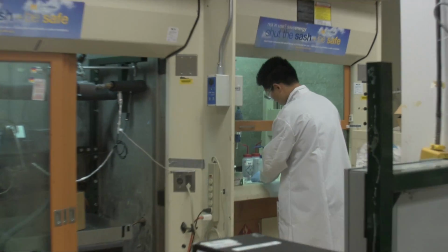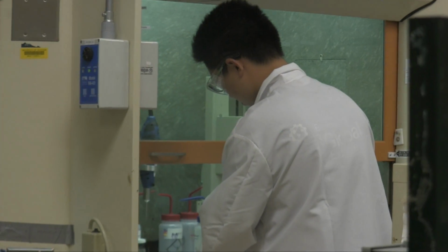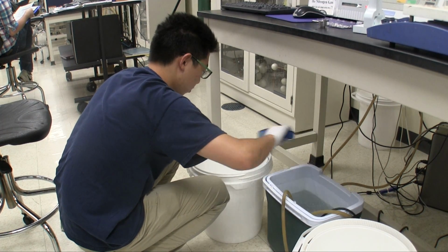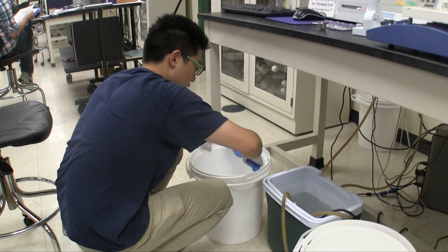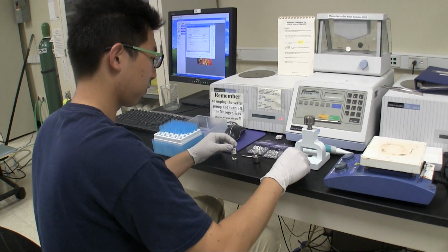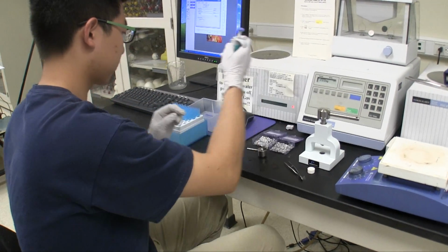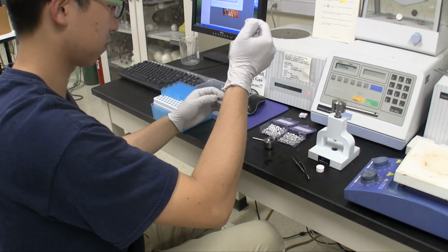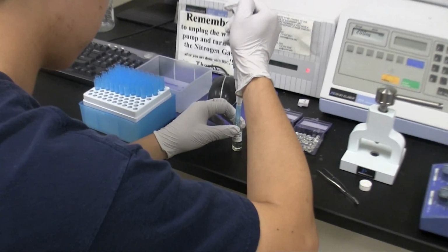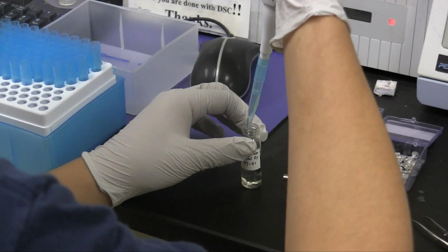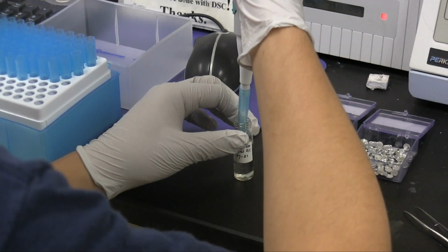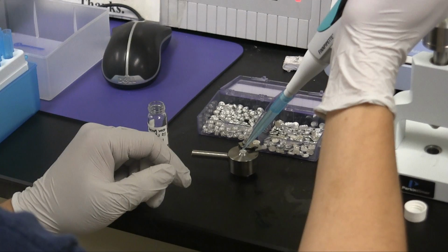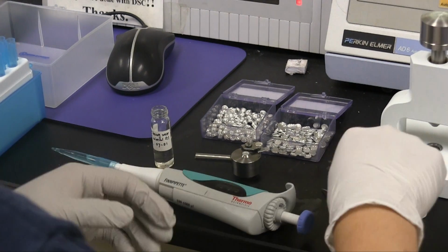My research can be divided into 3 parts. The first part of my research is to conduct DSC tests to get heat flow curves from different oil samples. I actually have several problems while doing the experiments. The first problem happened when I transferred the oil sample from the hot vial to the DSC pan. I noticed that the wax was about to precipitate when it touches the cold pipette, and I could see the cloudiness inside the pipette. What I have to do is to transfer the wax immediately from the pipette to the pan, so that no significant amount of wax would be left inside the pipette.